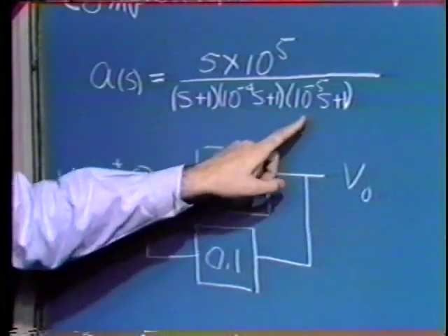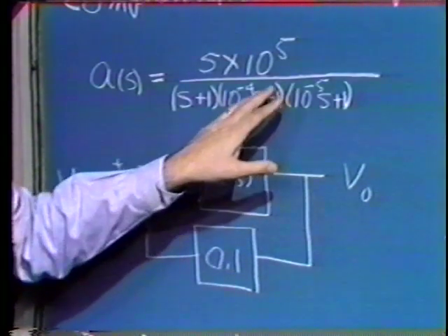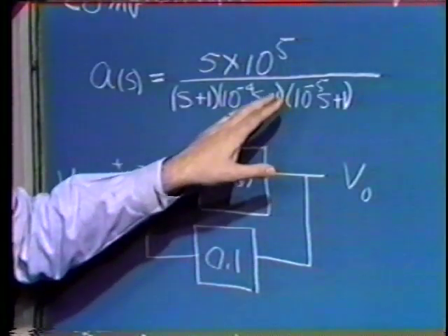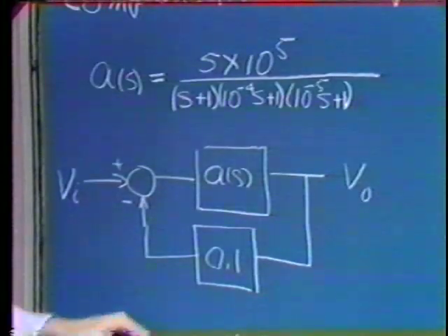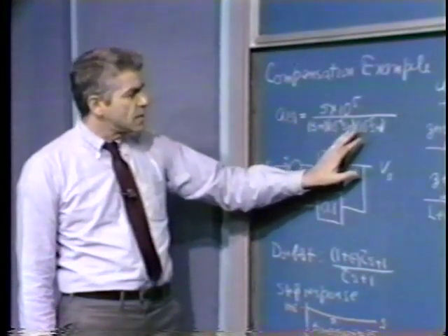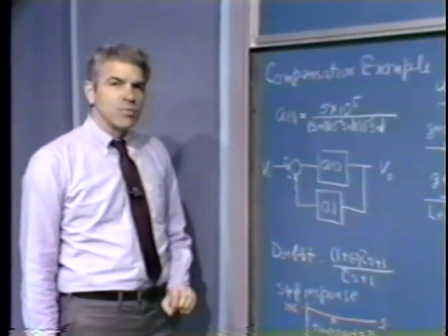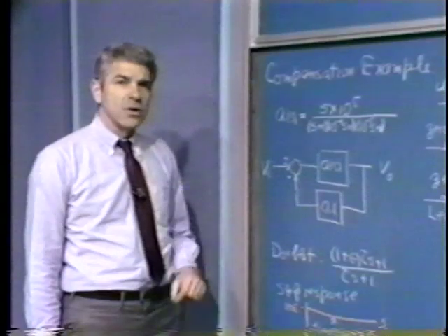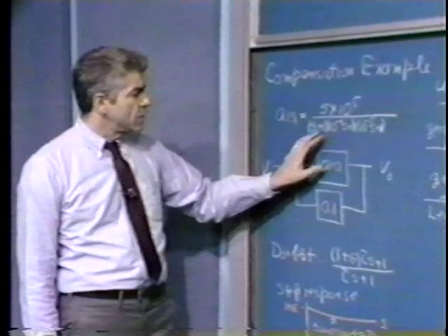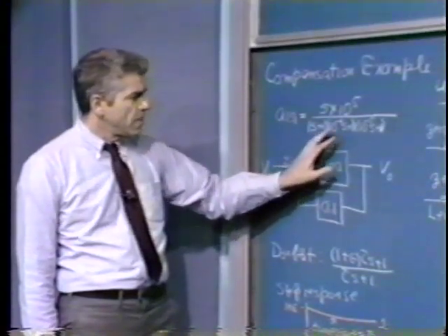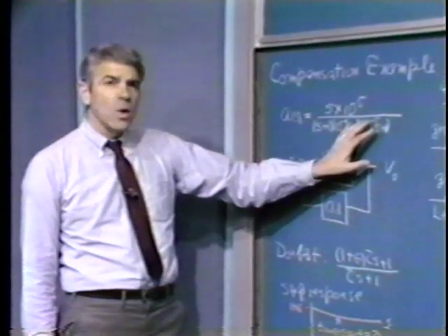It may be several additional poles, as I'm considering in this example. It may be, for example, time delays. When you look at certain kinds of transistors, you find out that they have a time delay associated with propagation of diffusion time delay. But anyway, these higher frequency dynamics give us additional negative phase shift and are ultimately the thing that prevents us from getting as high crossover frequencies as we might like to have. So this general form, where we have a single low frequency pole and then something else at high frequencies that gives additional negative phase shift, is quite a common pattern.